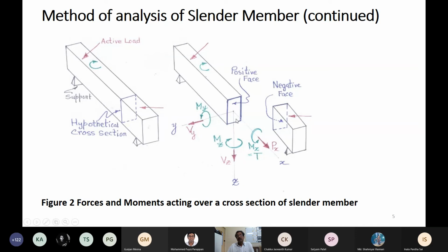I can say that if I correctly understand the magnitudes of these, this part of the beam, with the external force acting on this part, with the reactive forces and moments acting on this part, and with the six components of force and moment resultants acting on this cross section, all of this keeps this part in equilibrium. Similarly, equal and opposite to these forces and moments should act onto the other part of the beam which was separated out. So equal and opposite of these forces and moments should work here.